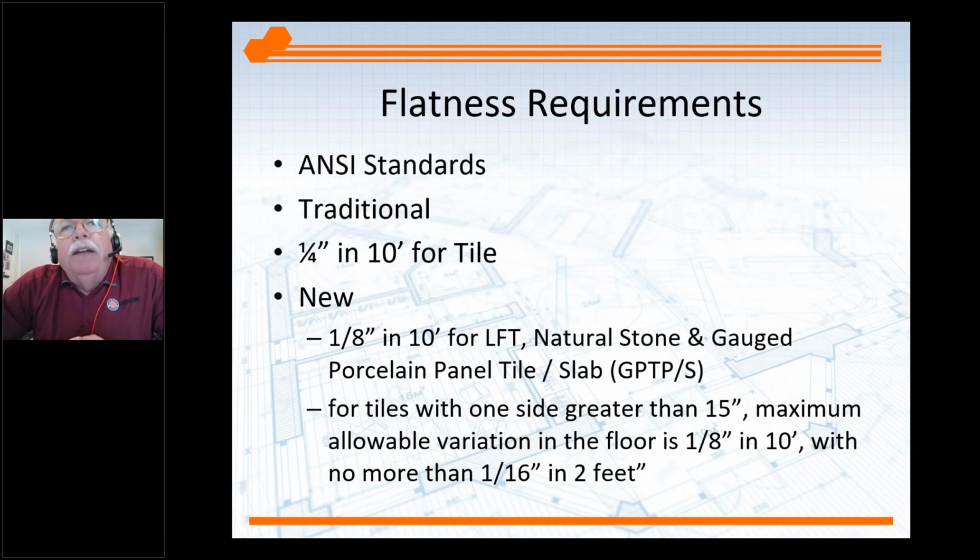So why does that matter to you? Because of the flatness. And there are ANSI standards. In the old days, 1/4 inch in 10 feet was flat enough for most of your smaller format tiles. As we got into these larger format tiles, we're looking at 1/8 inch in 10 feet now. And even for the porcelain panel tile slash slabs, the GPTPs, 1/8 inch in 10 feet.